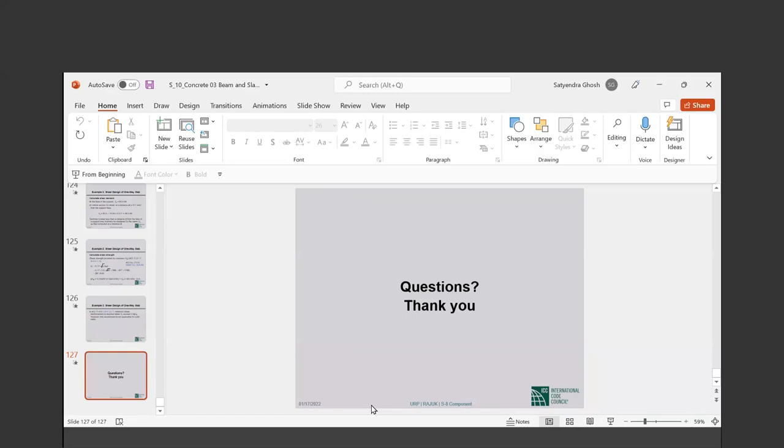Okay, Dr. Ghosh, are deep beams or transfer girders safe for earthquake zones, especially in a severe zone or moderate zone like in Bangladesh? That is a very good question. Well, we have a strong column weak beam requirement by which you cannot really have deep beams. At the same time, I hesitate to say that transfer girders are prohibited. I wouldn't go that far. How should I say? You have to be doubly careful in designing those transfer girders in seismic areas.